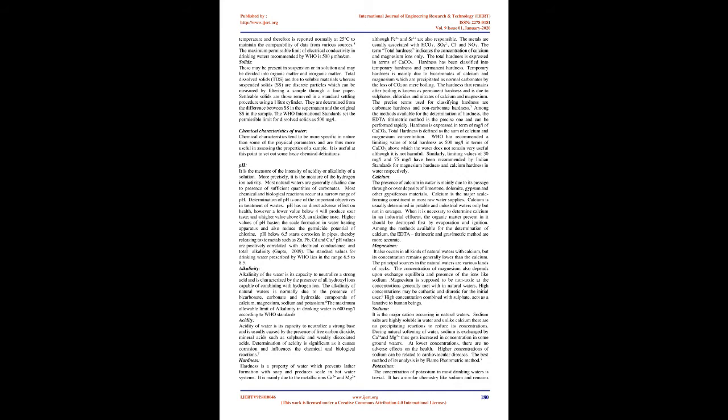Alkalinity. Alkalinity of the water is its capacity to neutralize a strong acid and is characterized by the presence of all hydroxyl ions capable of combining with hydrogen ion. The alkalinity of natural waters is normally due to the presence of bicarbonate, carbonate and hydroxide compounds of calcium, magnesium, sodium, and potassium. The maximum allowable limit of alkalinity in drinking water is 600 mg/L according to WHO standards.